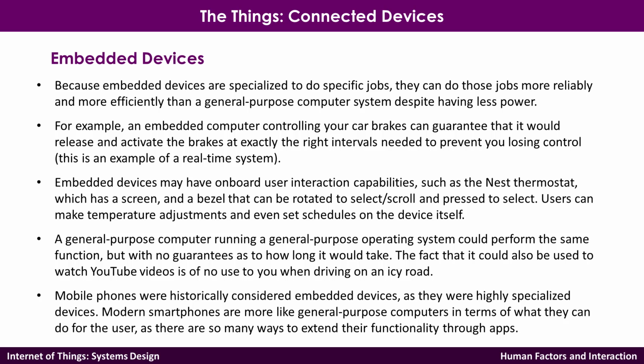Sometimes operating systems allocate resources to different applications, but they are not very good at understanding what is the highest priority in a particular given context, like driving a vehicle. On the contrary, these embedded devices are basically programmed to do one thing. If it is braking in a moving vehicle, it would focus on that particular task. So there are no competing applications looking for processing time in the embedded device, because the entire processing power is dedicated to this one task.